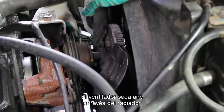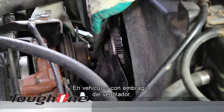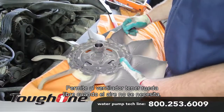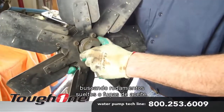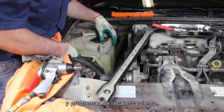The fan draws air through the radiator to assist in the heat transfer. On vehicles equipped with a fan clutch, the fan clutch engages as needed to draw air through the radiator. It allows the fan to freewheel when air is not needed, thus reducing horsepower loss and improving fuel efficiency. Check the fan clutch for loose bearings or oil leaks. Fan clutch failures can lead to water pump failures and overheating issues.